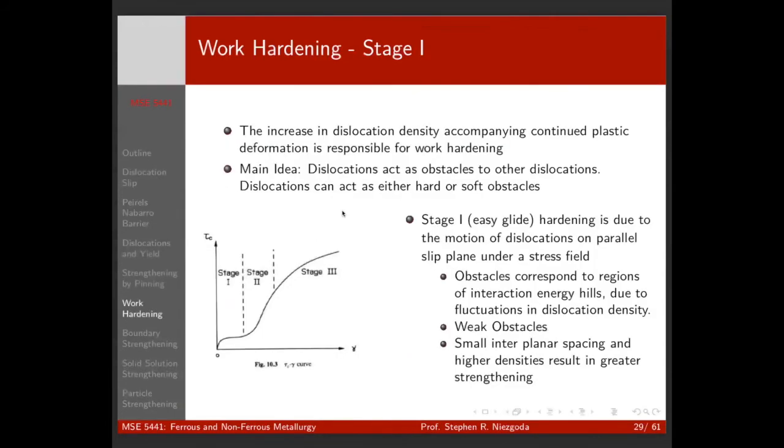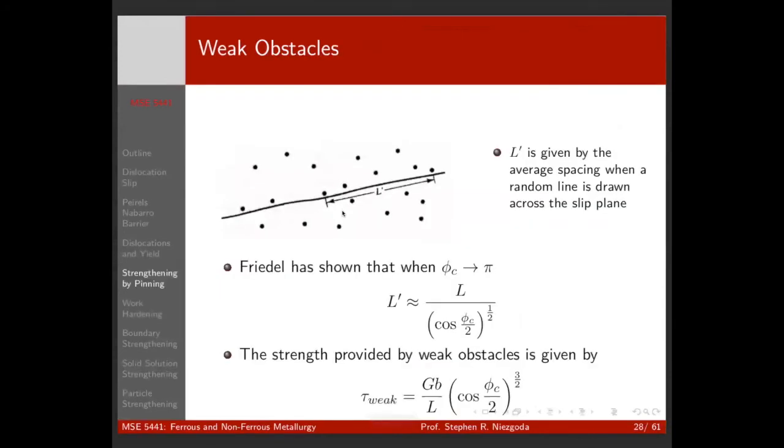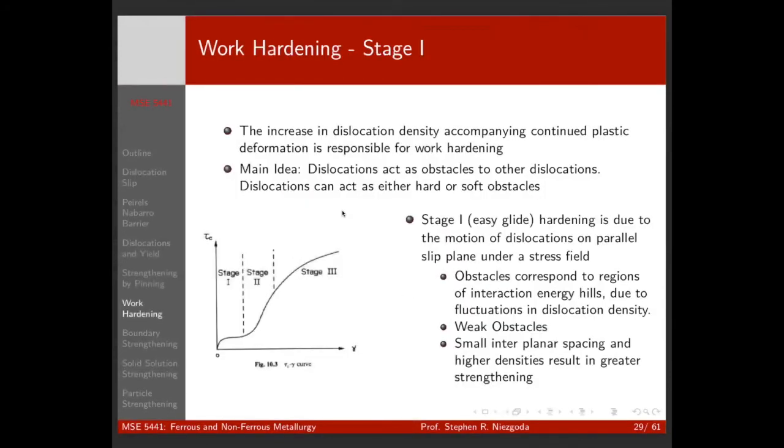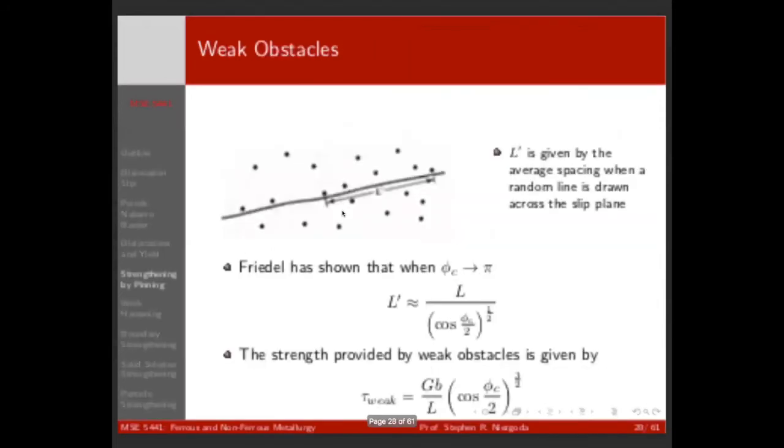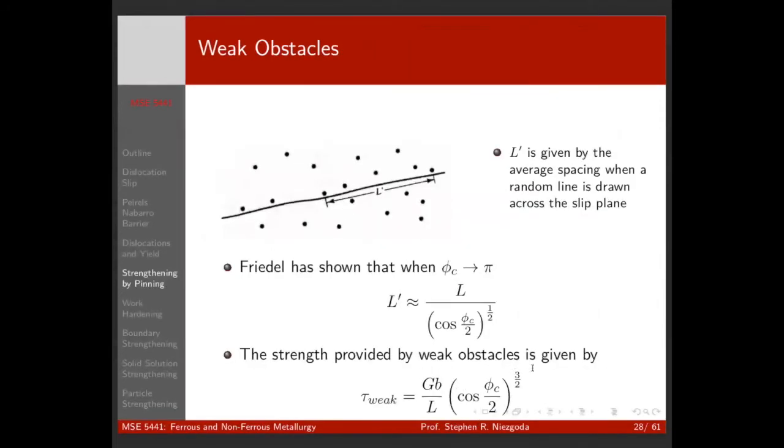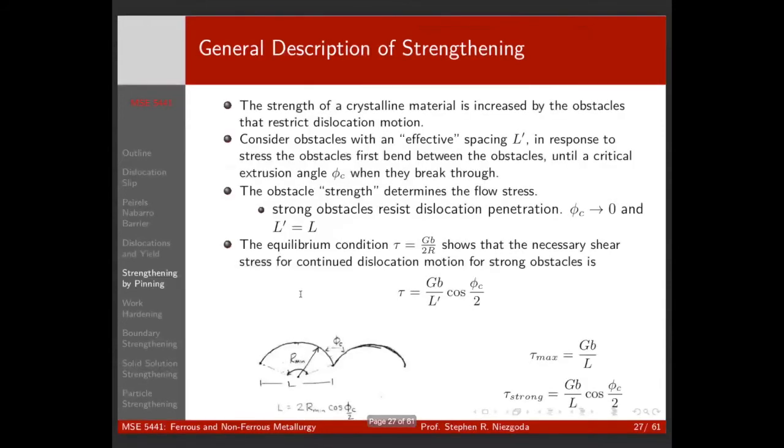So there's a lot of details I'm sort of skipping over in the derivations. And again, those derivations are not important. These particular final expressions are not important for you to memorize, right? It's just this idea that when the obstacles are weaker, the dislocation line remains straighter, and the distance between pinning points is much larger than the effective obstacle spacing, or the actual defect or pinning point spacing. Whereas for strong defects, it is actually the particle separation that matters.